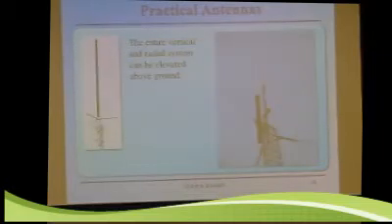And something else, as we'll see here, if you are high above the ground by wavelength, remember by wavelength, a 2-meter antenna would be very high above the ground, 3 or 4 radials are about all you need. HF verticals are typically on the ground or right at the ground. But if you can get several wavelengths above the ground, then you don't need so many radials, just 3 or 4 will do well.